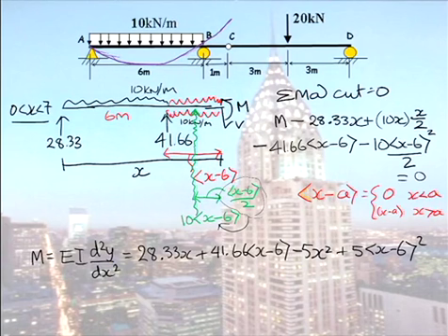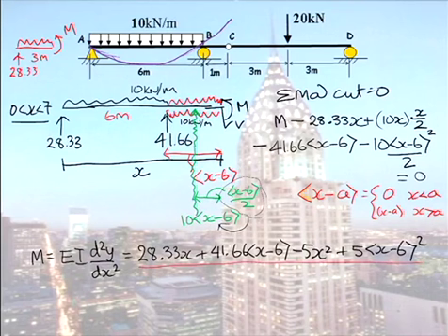So looking at our current problem, if I cut the beam at, say, 3 metres, so if I now draw over here my free body diagram, cutting at 3 metres here, can you see in there I haven't come across the reaction at B, 41.33. So if we look at our expression here for our moment, because x is less than 3, that term would disappear.